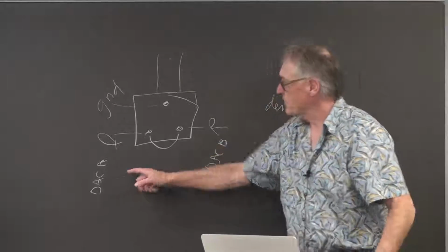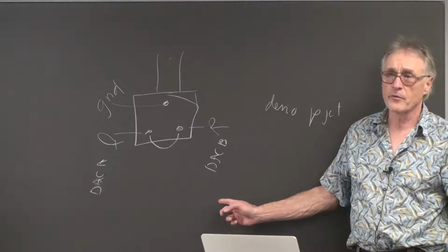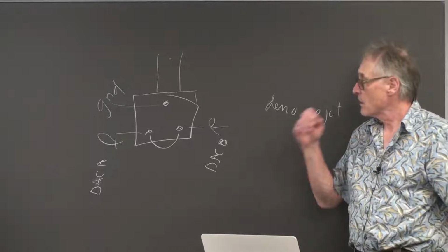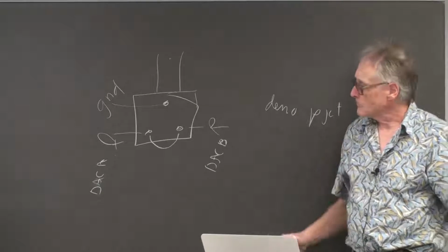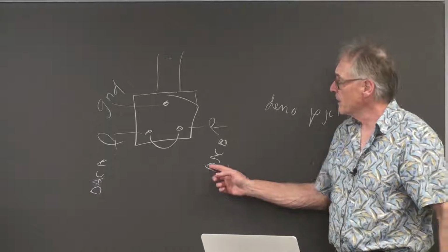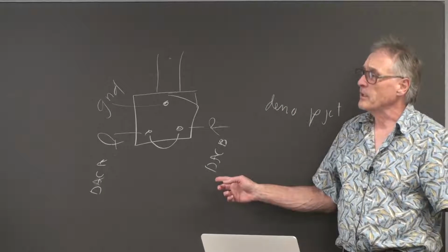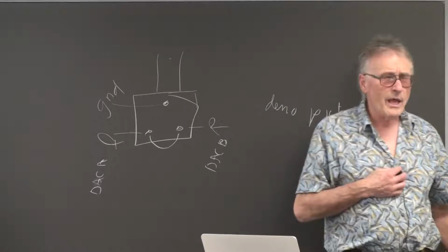If the DAC outputs are both very low impedance, it'll just destroy the output stage of one channel or the other or both. If they are fairly low impedance but high enough that neither of them is destroyed, what will happen?